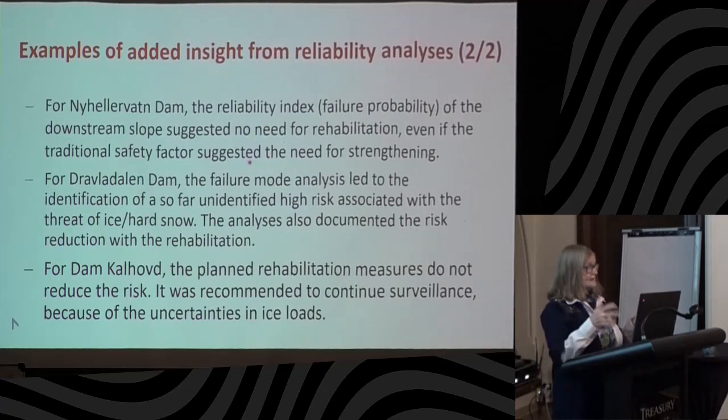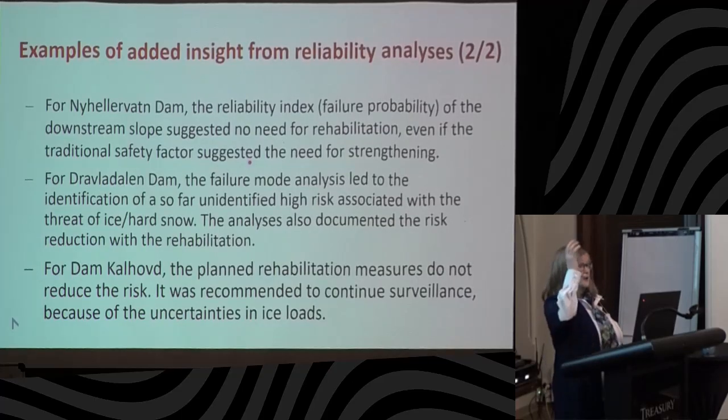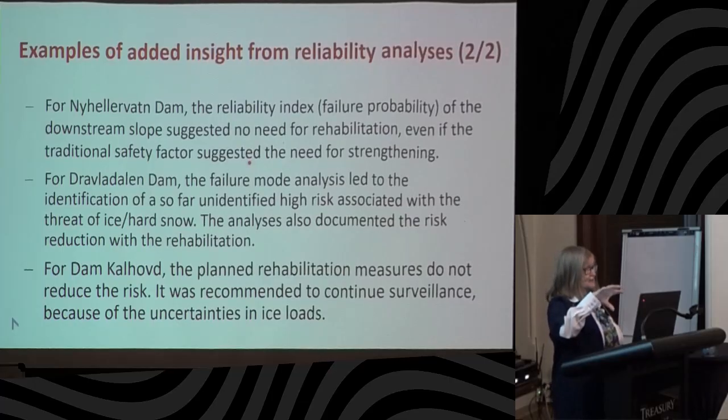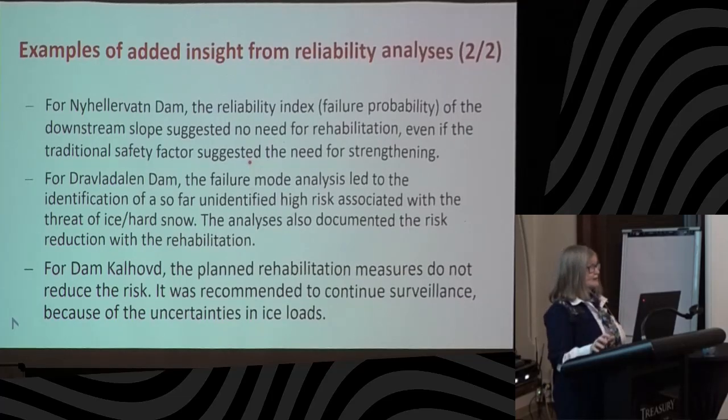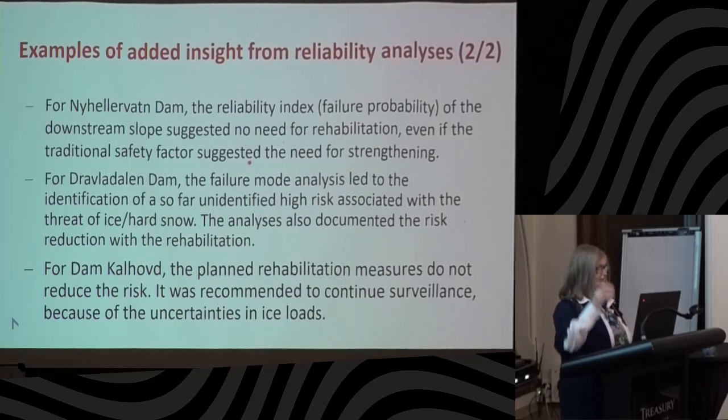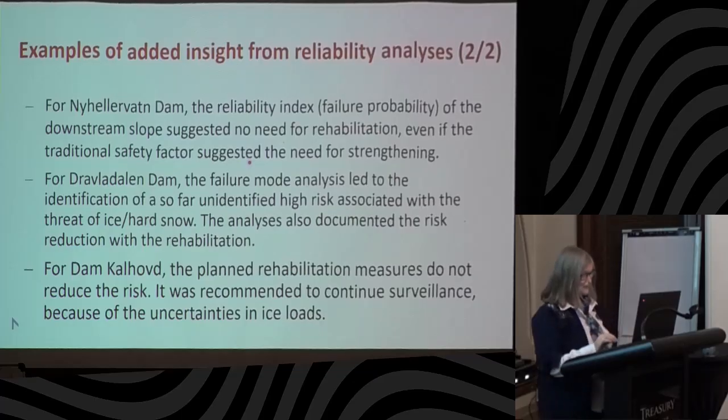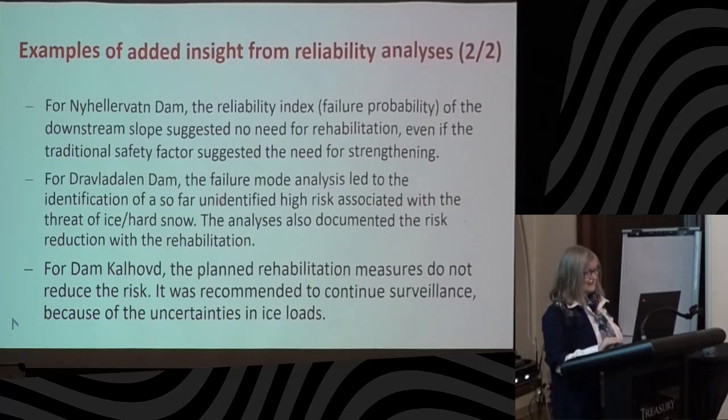And then one of the inspectors, the dam responsible who goes and looks at them in the winter, says, yes, and what happens in the winter? The ice goes into the tunnel or the spillway and it stays there until June. But our snow starts melting in March, and when it starts melting, it's very fast on the top of the mountains. And so we get all this water and the spillway is blocked.